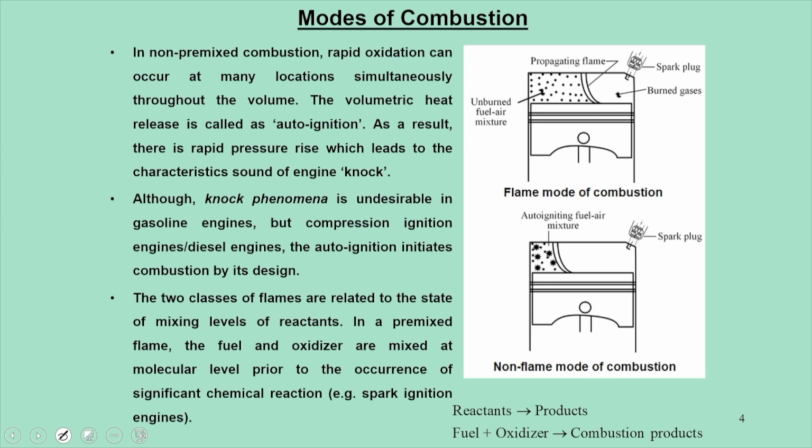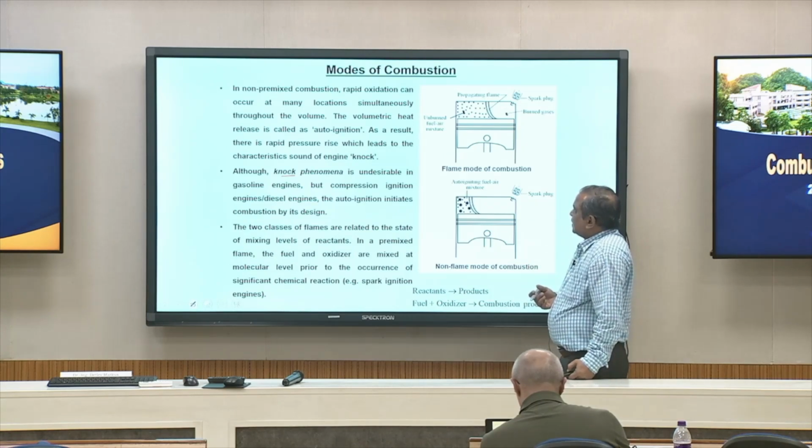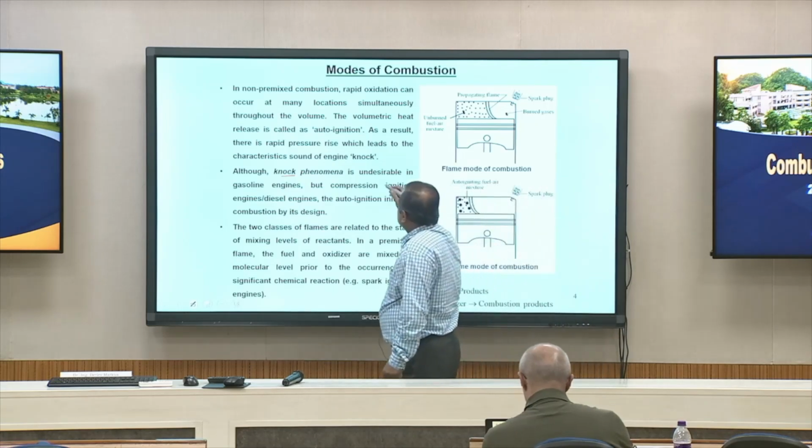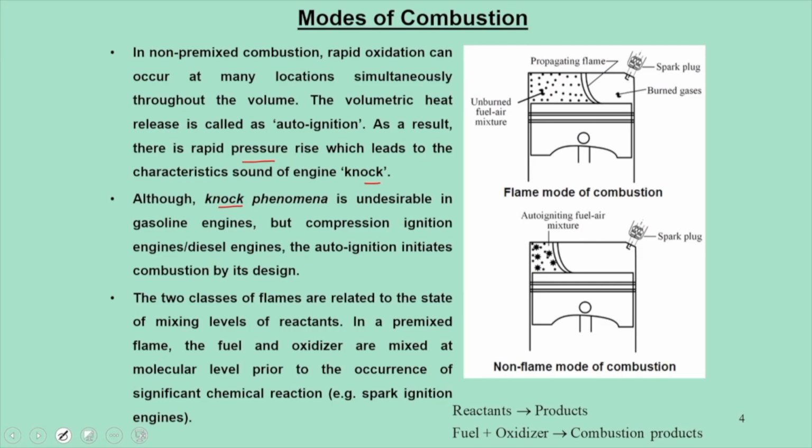Many times, from the engine point of view, if the charges are not ignited completely, it creates an effect called knock. This knock is an undesirable situation that we encounter in the cylinder of an IC engine, and it is quantified in terms of rapid pressure rise, and it leads to an undesirable sound of the engine. So we'll talk about how this knock forms in subsequent slides.